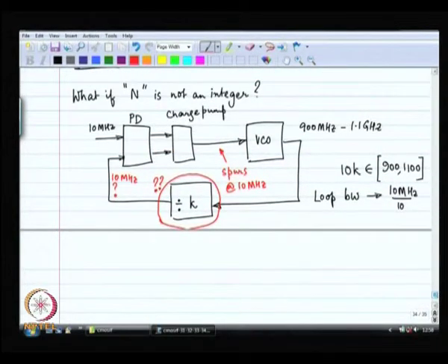So, everything is fine in theory. On paper it looks like this is going to perform better. It is definitely going to perform better in terms of phase noise, it is definitely going to perform better in terms of settling time. Performance in terms of spurs, it looks like it is going to be better on paper, we will have to examine that. The only question mark over here is what is inside this division by k.